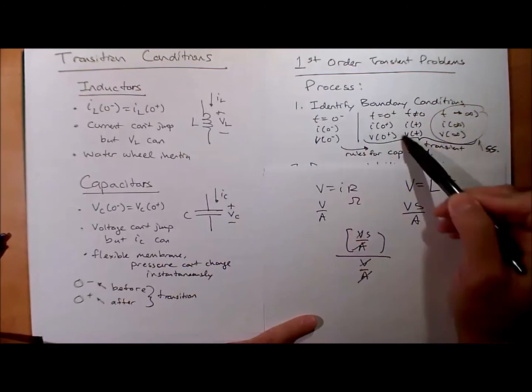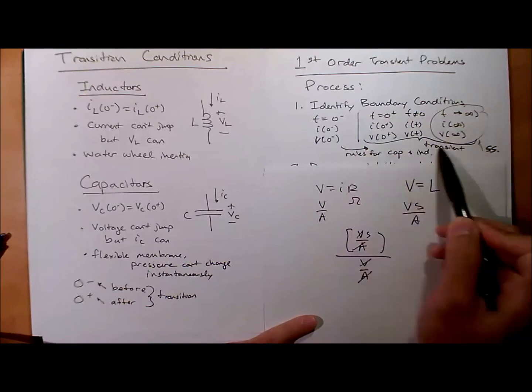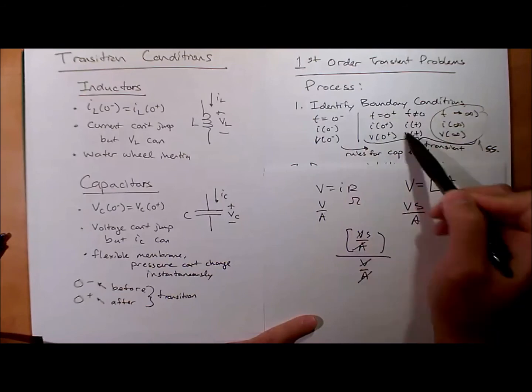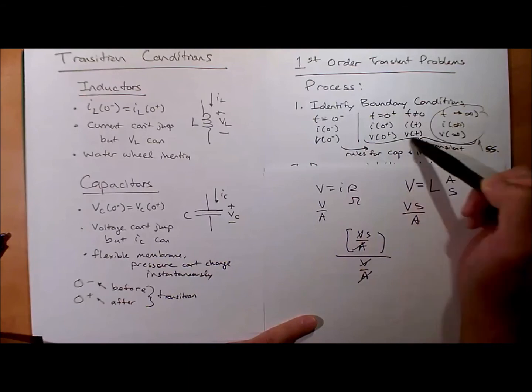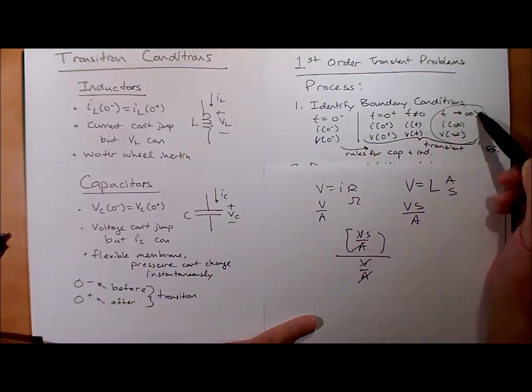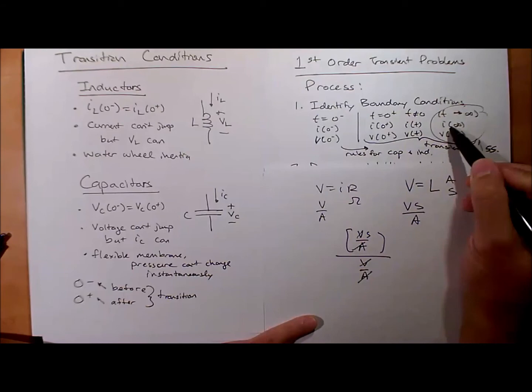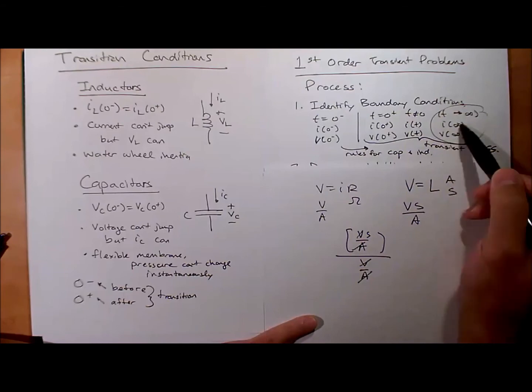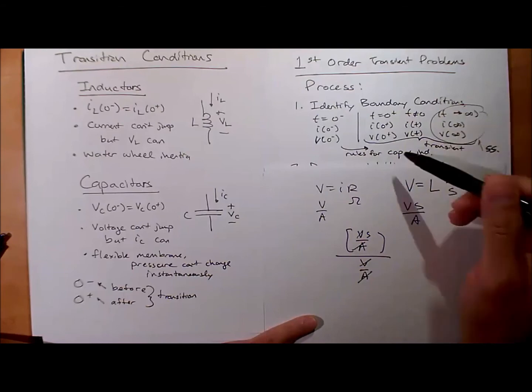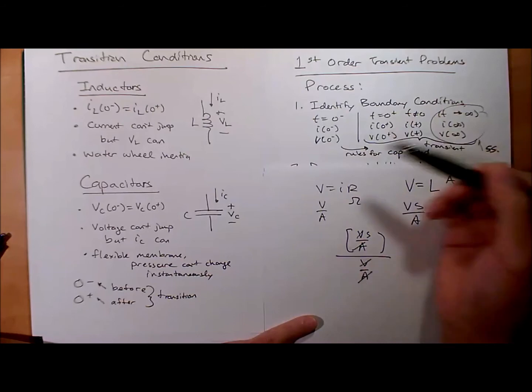Then over here, after in your transient condition, you might go, oh, okay, this we know is where we apply the first order differential equation process. But if we're looking for the boundary conditions, we might fast forward and look at what happens as time goes to infinity. Okay, so as time goes to infinity, we might want to know, well, what's the current and voltage? These could be boundary conditions that you could use to plug in and solve for the K1, right?